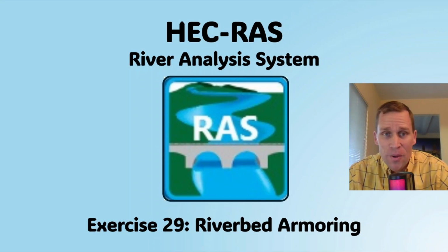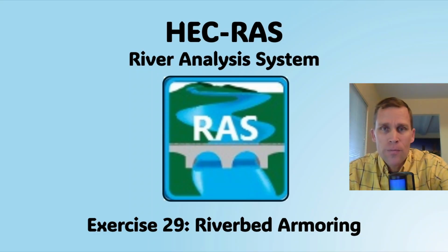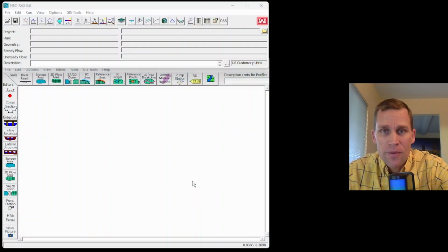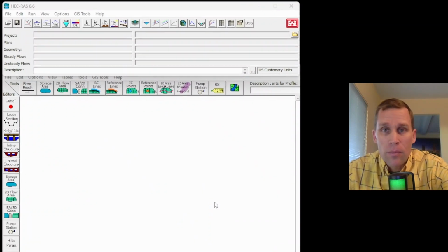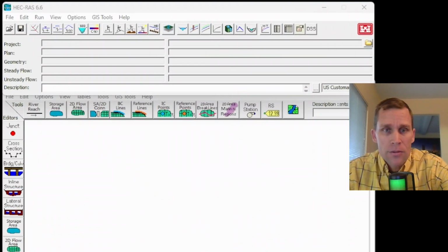Welcome and hello. This is a video exercise in HEC-RAS, and in this exercise, I'm going to be demonstrating riverbed armoring. What that means is, if you have sediment in a river that's eroding, then we can put a second, larger gradation layer on top of that native layer, and that will prevent the erosion. So that's what's meant by armoring. Let's go ahead and get started.